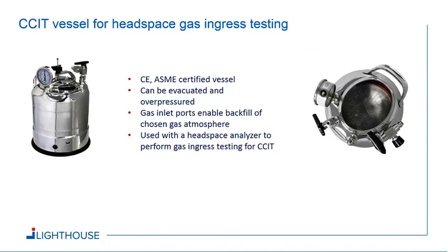So I wanted to show you an example of a CCI test vessel, CCIT vessel, for headspace gas ingress testing. This is something that we actually provide. You can see that it's a CE and ASME certified vessel. You can overpressure it to multiples of atmospheres. It can be evacuated, and you see the various gas inlet ports on this chamber or this vessel, and that enables you to backfill the vessel with a chosen gas atmosphere and then seal it.